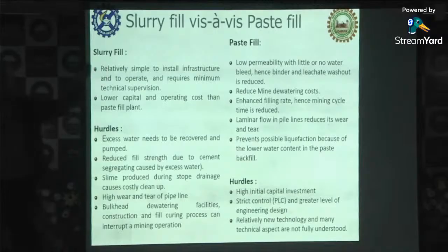And when dynamic loading like cyclic loading comes, at an instance when resonance is there, particles vibrate with their natural frequencies, and when the external frequency comes, like from blasting, the whole mass becomes fluid because the pore water pressure exceeds the confining pressure. That is the main danger for low concentration fills. But in case of paste fill, that is not an issue because whatever water is there is for hydration and all that. So possible liquefaction is prevented.